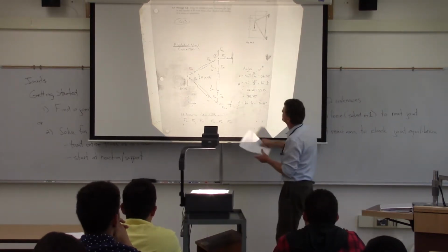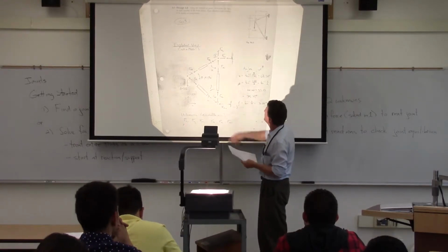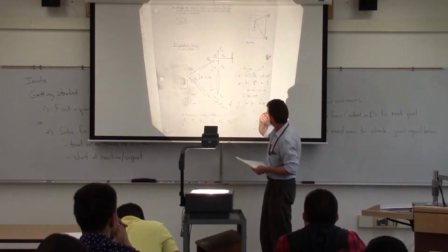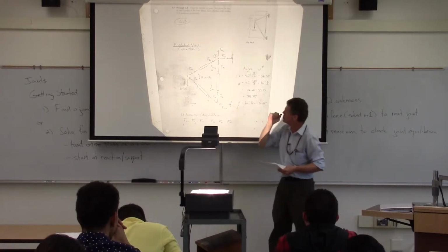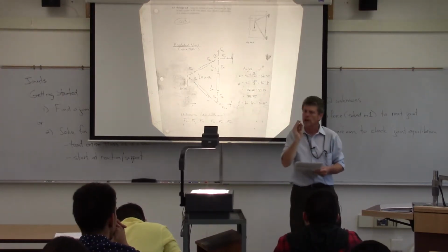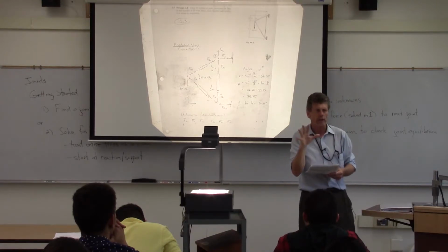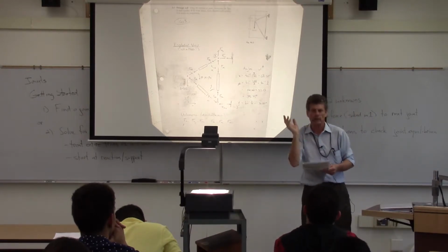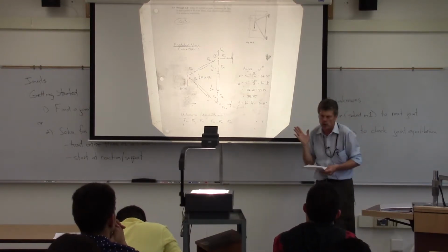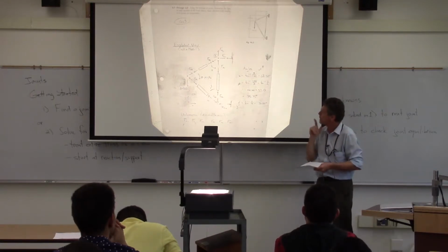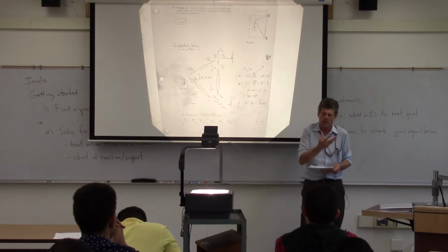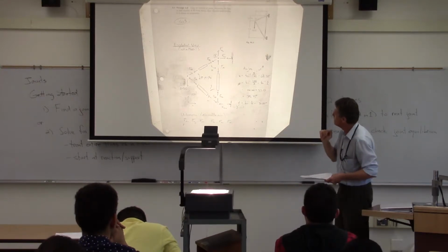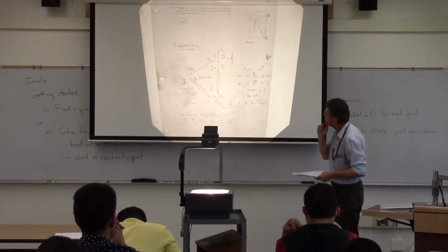Same thing with all the other ones there. We just shrink them basically. We assume that one's in tension, or this one in compression actually, I'm sorry. We're assuming it's in compression. Now again, the nice thing is with statics, sign will basically correct us. We know the direction. We can pick a direction, we can pick a sign. If it's the incorrect direction, basically signs will correct us. And we'll go through the problem solving it that way just to see how it goes.